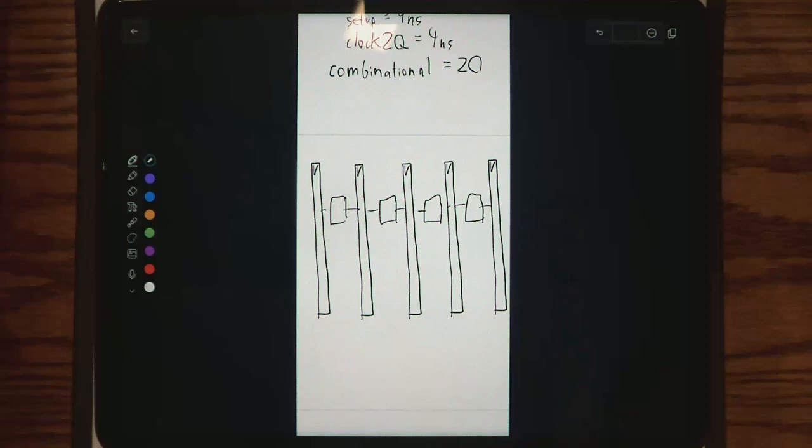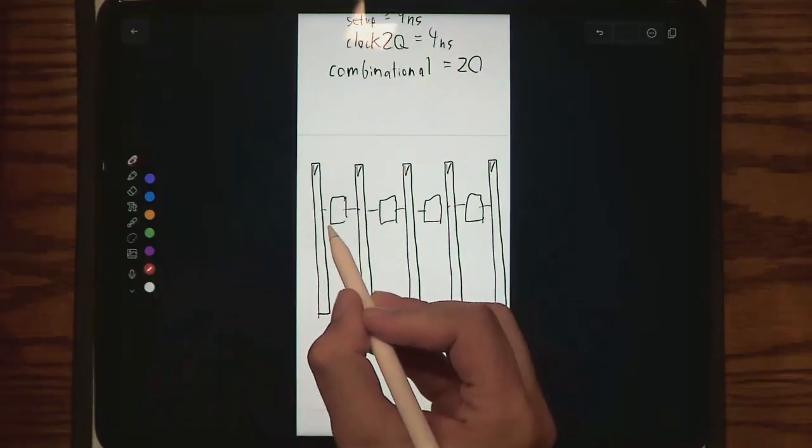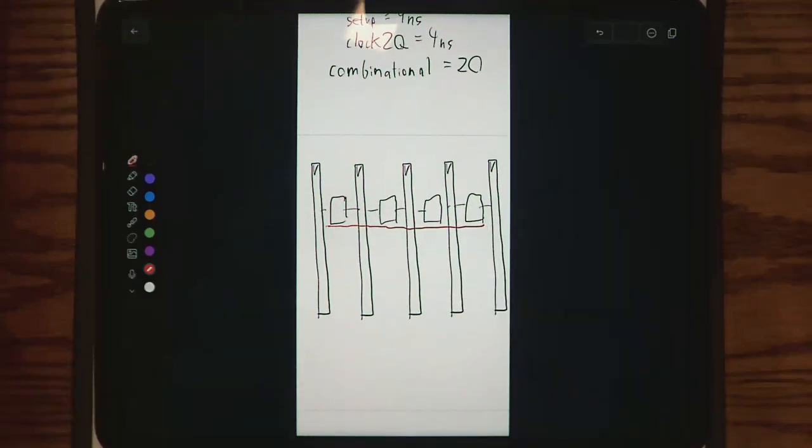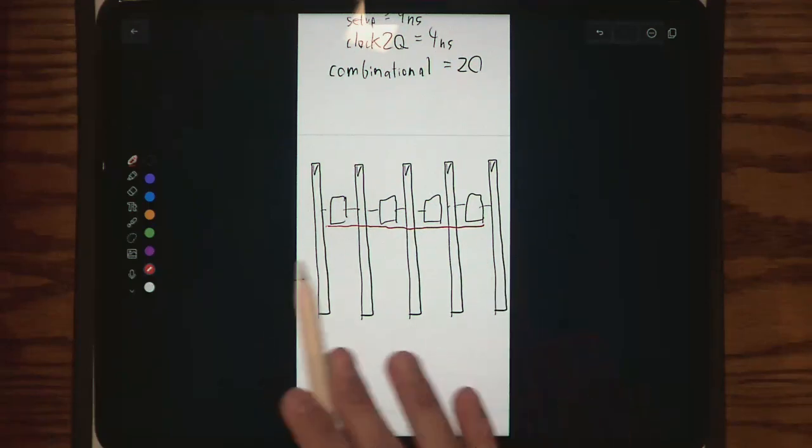Yeah, another question. You said implementing that pipeline would overall be slower. Can you explain why that is? Yeah, I think I'll talk a little bit more on pipelines on Wednesday. But the whole idea is that now you have to factor in all of the delay introduced by all these flip-flops. So your clock frequency goes up, but the amount of circuit that your signal needs to propagate through is actually increased. So now your data needs to propagate further and further. So your total latency, latency being the term for how long it takes for your output to be generated, will go up, because there's just more to go through.